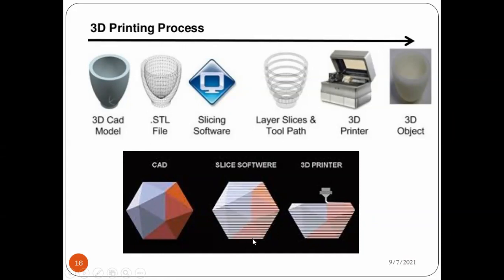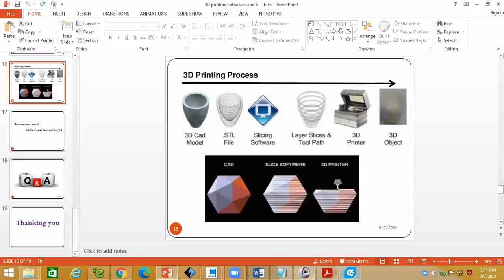Now the bottom layer is taken and printed first. Next the n-1 layer, n-2 layer, like that, it goes from the bottom to the top. Based on this layer information, the 3D printer nozzle, laser, or head will move. You have to create this layer information using our 3D printing software. One of the softwares is Cura, which is open source software.